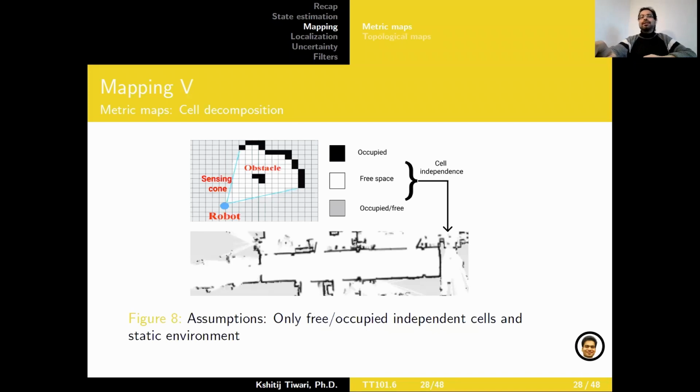So what does that mean in terms of the occupancy grid that we were talking about? As I said, occupancy grid is basically discretizing the environment into grids and then checking the occupancy of the grid cell. Okay, so this is your grid environment, and the cells typically have three colors. If this is your robot, the blue lines represent the sensing cone. Let's say it is using a typical sensor, it could be a laser rangefinder for the sake of argument in this case. Then this sensing cone represents the current region that the robot can sense from its current position and orientation.